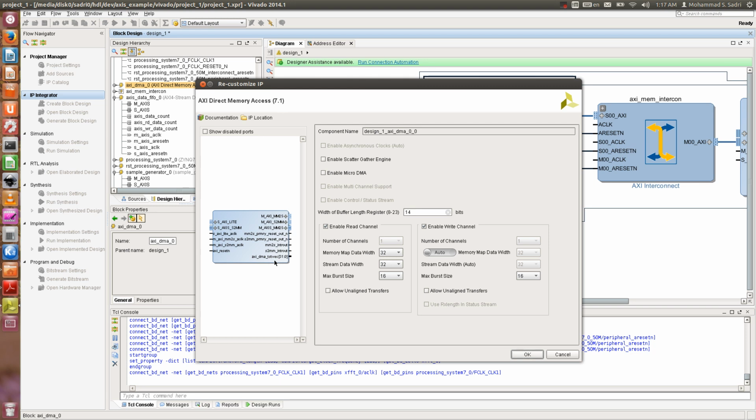For example, if the CPU configures the DMA engine to transfer 1 MB of data, after this task is done, an interrupt will be generated by the DMA engine to the CPU, and the CPU should come again and reconfigure the DMA engine for the next transfer task so that the next data transfer can begin. In many of the applications, that is okay. It doesn't drop the performance of the CPU really, since the interrupt rate is small.